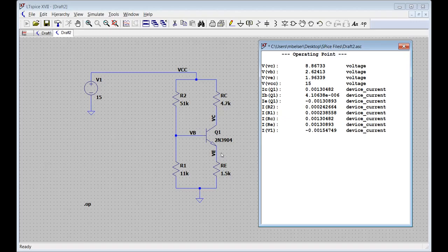It's been a while since I taught Electronics 1, and I don't know if they actually teach checking to make sure that your transistor is in the correct region of operation by checking your voltages here. So we talk about the base being greater than the emitter if this is actually on and current is flowing. So this minus 0.7 gives me VE.